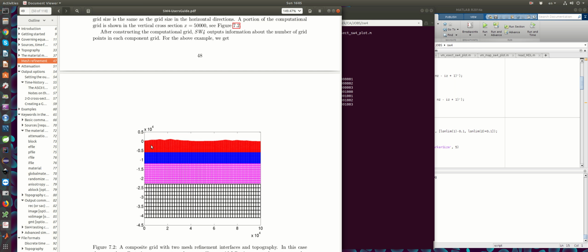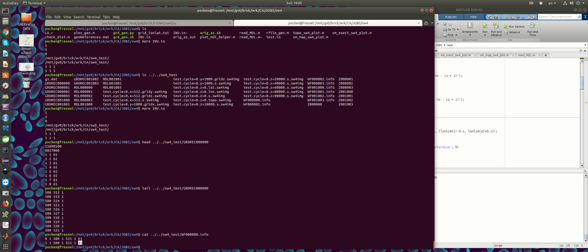If we look at this particular figure, that's the interface. The curvilinear grid is this grid, that's grid 1, and the Cartesian grid, the uniform mesh, is grid 0, right? At this interface, the z coordinates are identical. So inside the skg.py Python script, it's going to try to remove this duplicate z coordinate.